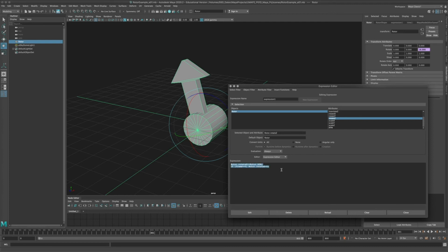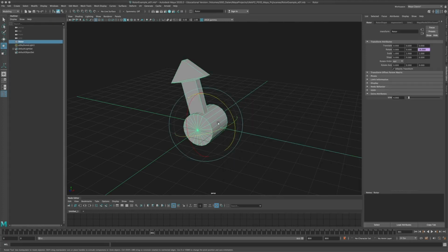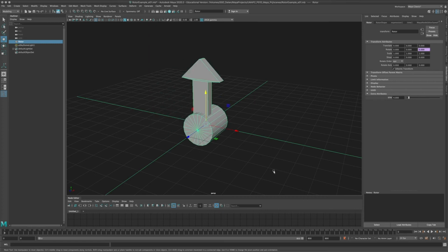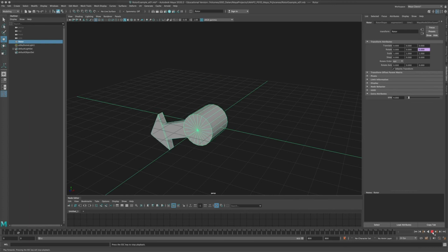So instead of rewriting that expression, you can bake that down, which means you're breaking your rig before rendering. I did it for the propeller because I find it natural and easy to just use an RPM value instead of animating curves, but I do have to bake down the propeller. So what does that mean? This is the animation as I like it. It's 4 degrees per frame, and it's doing its thing, and it's wonderful.